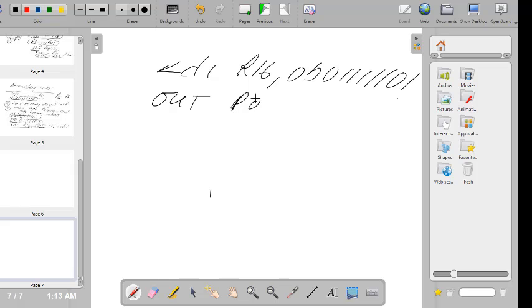I'm going to say PORTA, comma R16. What is on the right is being loaded to the left. So I'm loading this number into R16, and then I'm outputting what is in R16 to port A.